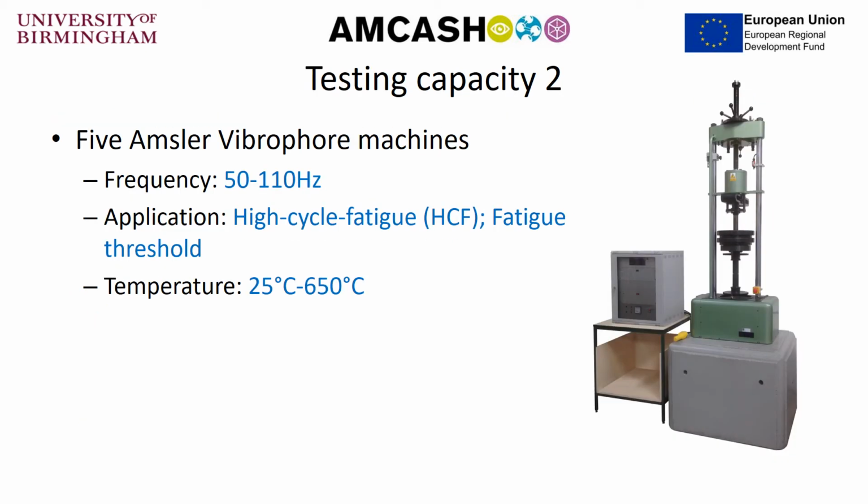In our second mechanical testing lab, we have 5 high cycle fatigue machines. These are capable of oscillating at between 50 and 110 Hz frequency, and they can determine a material's fatigue threshold point. They can operate in a temperature range from room temperature to 650 degrees Celsius.